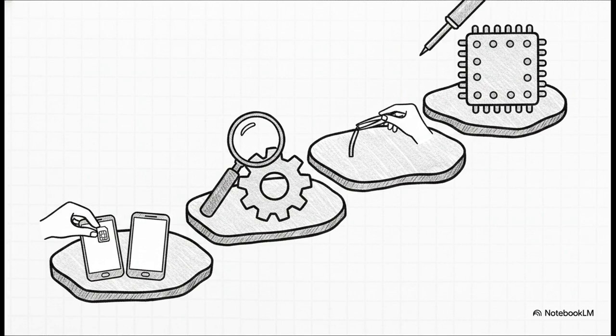You don't just immediately tear the phone apart. First, insert the SIM in another phone to isolate the issue. If it's not the SIM, manually search for the network in your settings. If that fails, okay, then you open the phone and clean the antenna tips. Still offline, you escalate your operation to heating or changing the antenna switch. And if all else completely fails, you escalate all the way up to reballing or changing the main network IC chip.